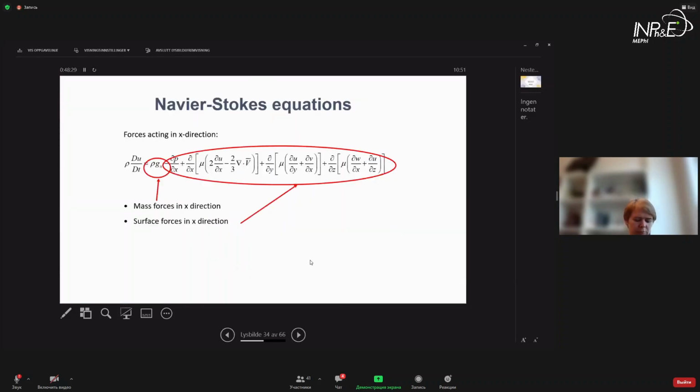So before we continue, just to sum it up, here is what Navier-Stokes is. And this is one way of deriving these equations. You have probably seen several more, but this is the one that goes through a very basic, down-to-earth approach: simply thinking about Newton's second law and forces, the sum of forces which act on a fluid particle, creating the acceleration of this particle and deforming it at the same time. So as you can see, we cannot simply solve it.